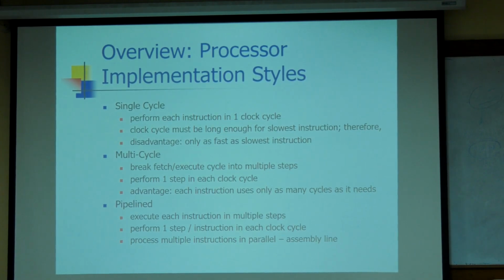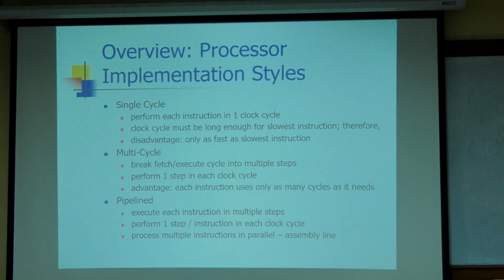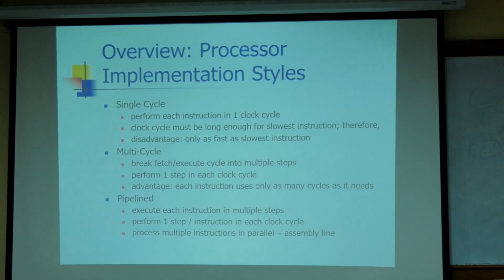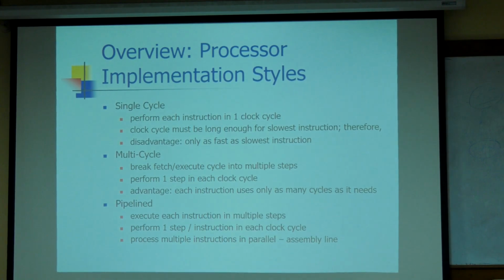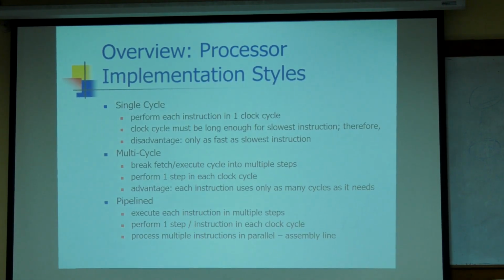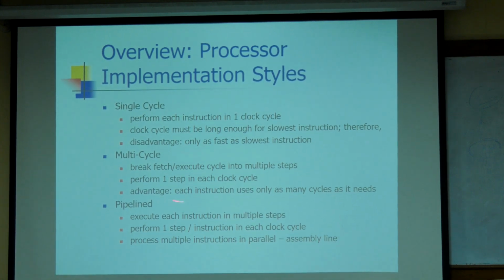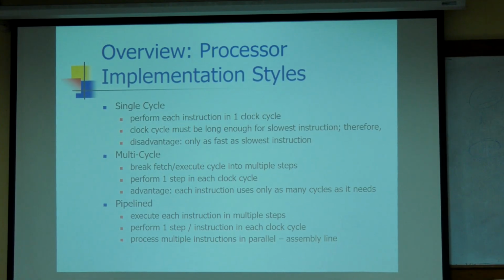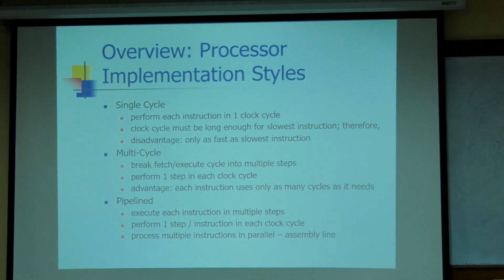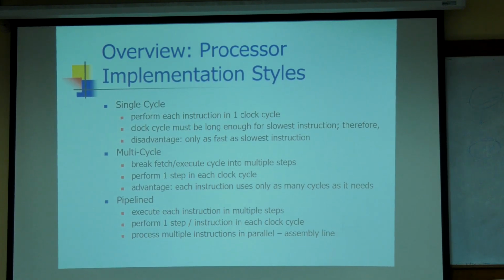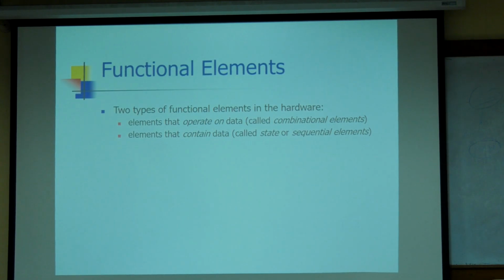We can also develop that; there are advantages and disadvantages of single cycle and multi-cycle. If you go for multi-cycle, it takes multiple clock cycles, but the clock period will be less, so we can run the instructions efficiently and improve the throughput also. But here the cycle period is decided by the longest instruction, the one that takes the most time, and that will decide the clock period.